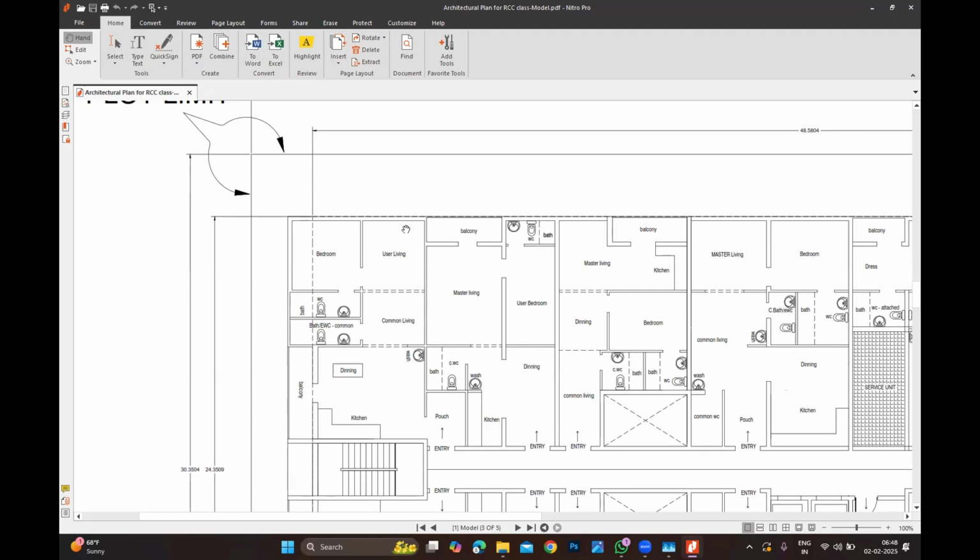Those people who are experienced in barrels, it will be like 40 meters, 50 meters. Now, why is it not going to work here? The thing is not about the columns, it is about the slab. If you increase the spacing, automatically the slab thickness increases drastically. There are only two elements where you can do value engineering: one is the slab, another is the beam.